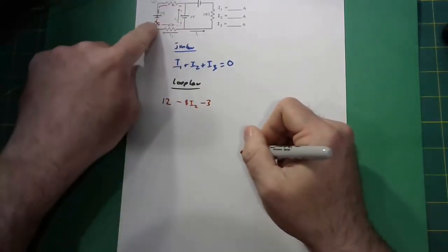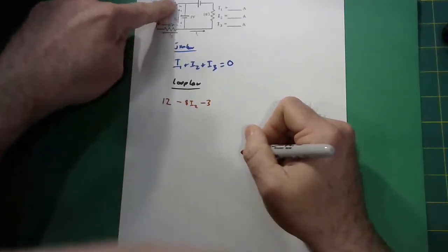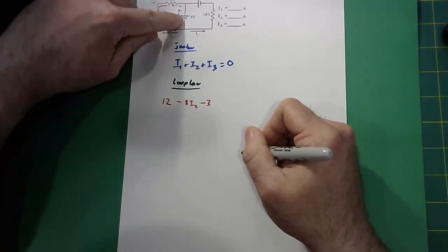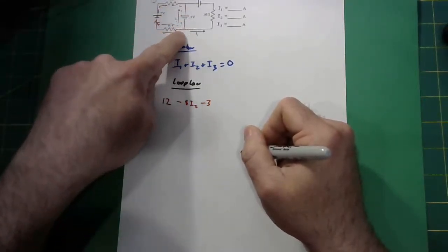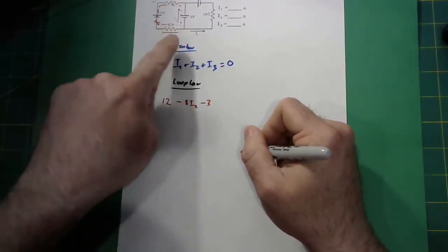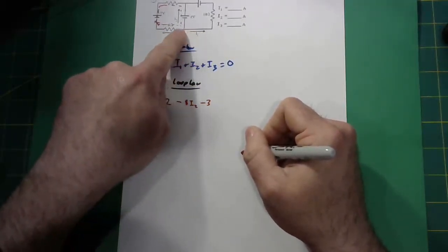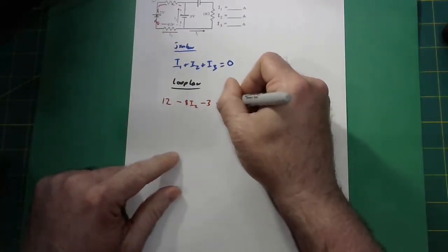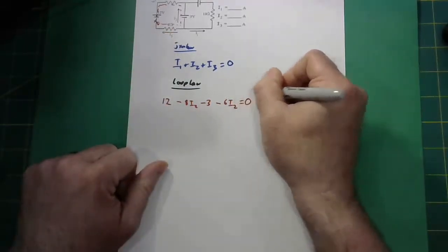Now a setup like this will happen when you're recharging a battery. You'll have some higher voltage here that's going to push charges backwards through this. It'll make the little chemical reaction inside the battery between the 2 metals run backwards, and you'll be recharging the battery. So that's one reason why you would have a battery set up like this. Current's going to flow around. Now I'm going with I2 through the 6 ohm resistor. Again, I'm going with the current from before it loses the energy to after it loses the energy, so I'm going to go down IR, down 6 I2. That gets me back to my starting point, so that's equal to 0.